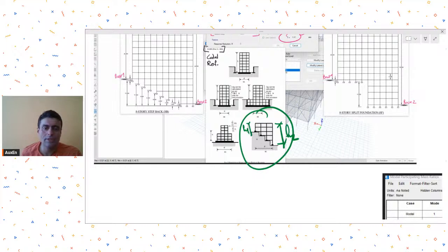Smaller height h1 means time period will be smaller, which would mean that you are getting a more critical SA by G and more critical AH value. So while calculating time period, this is the concept that you should use. Take height as low as possible.